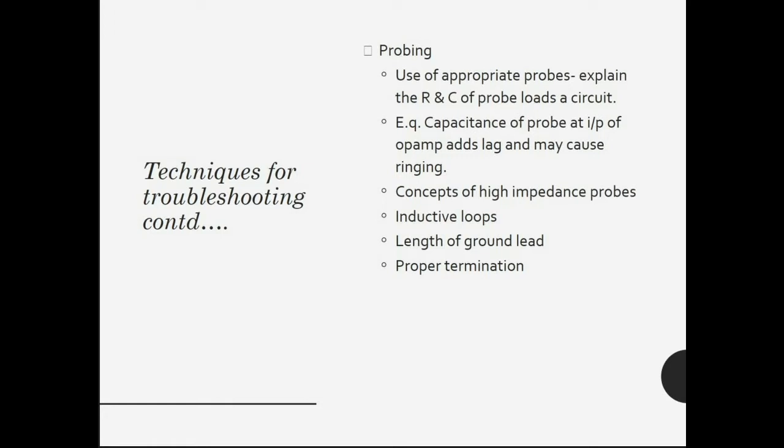By attaching the oscilloscope probe to this, a quick adjustment can be made. However, if the leading edges of the spike rise too high, falling back to the required level, then the high frequency response has been enhanced and this needs to be adjusted.